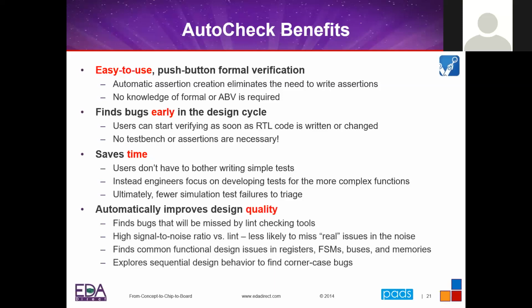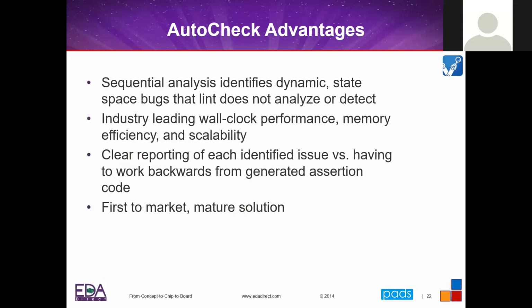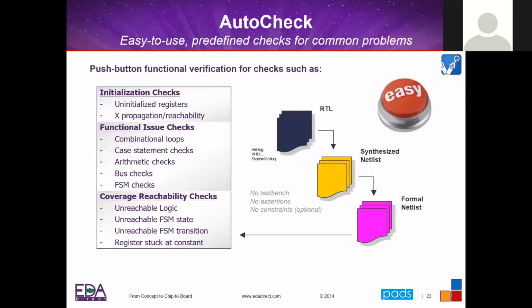And it really just improves the quality of the code that's coming into your verification effort. So it's more than just a static linter, as I said, because it's using this formal engine to do a state space analysis. It's very fast compared to simulation, and then it's really good for reporting and debugging those issues.